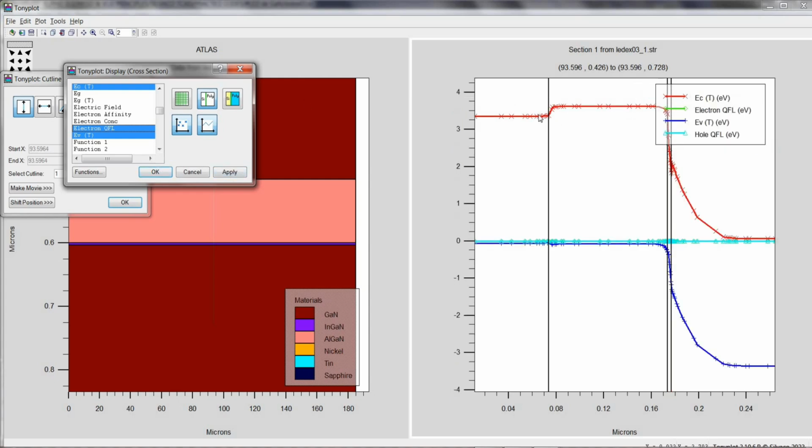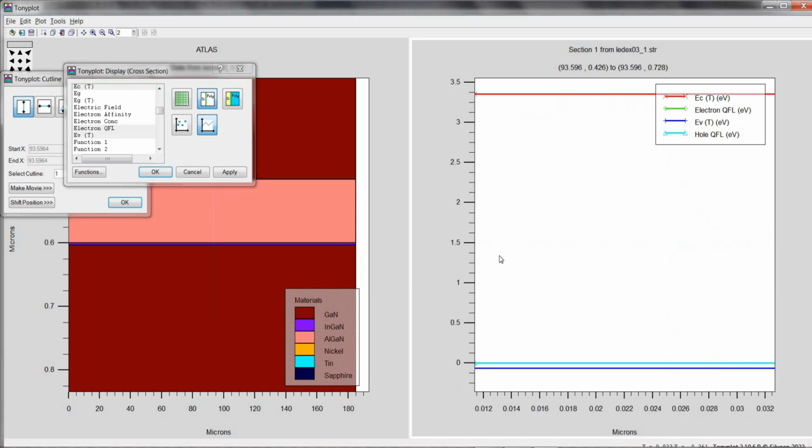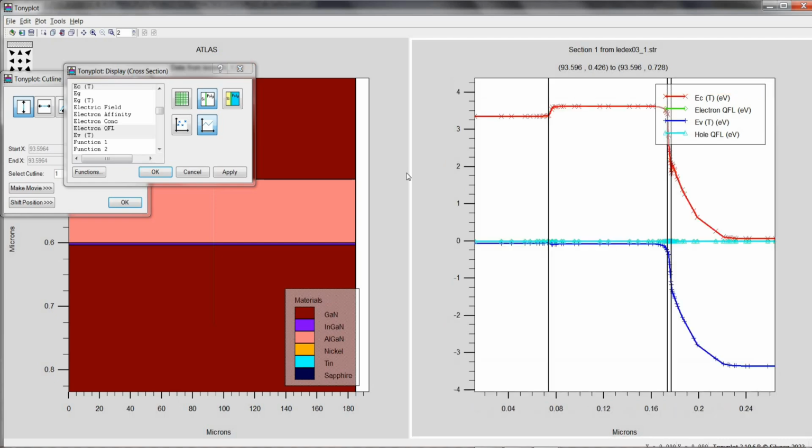And we also see these interfaces, like to the left of this line we have the p-type gallium nitride region, and you can confirm it from the energy band gap as well. This is the conduction energy level, this is the valence energy level. So the difference between these two over here is around 3.4 electron volts. So this is our p-type, and then the Fermi energy level is closer to the valence band. So this is our p-type gallium nitride there.